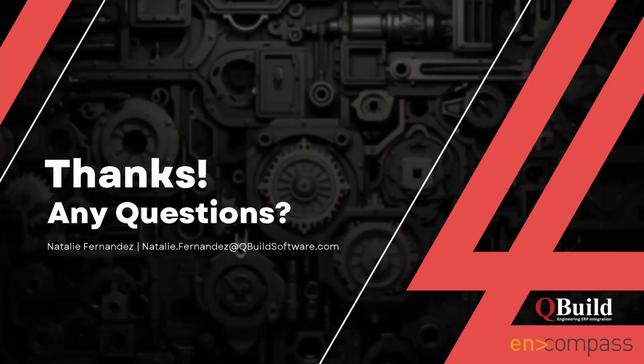Can CADLink collapse CAD assemblies to a flat BOM? For example, a lock might be an assembly with its fasteners in CAD for convenience and consistency. Yes, we can. We do have a flat BOM or single level BOM setting. So CADLink can pull in that multi-level BOM if you have it. But if you only want CADLink to bring in a flat BOM to Epicor, it's just a matter of clicking a checkbox in the settings.